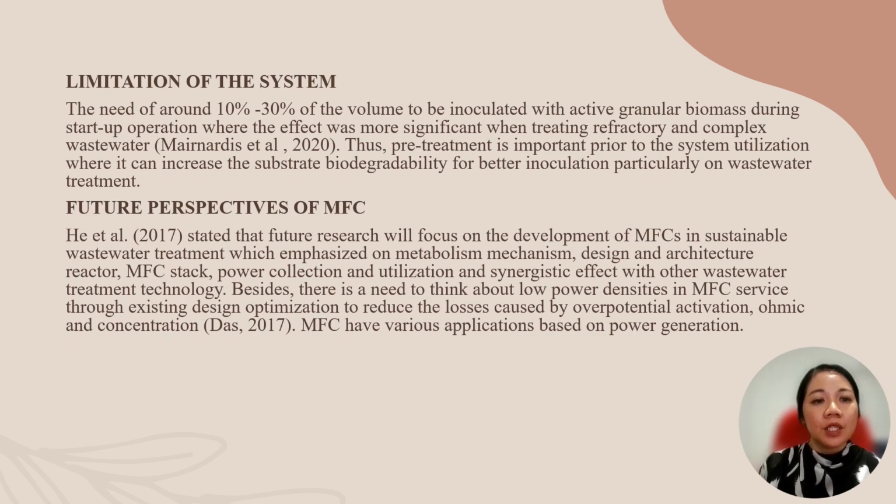Limitation of the system: the need of around 10% to 30% of the volume to be inoculated with active granular biomass during startup operation, where the effect was more significant when treating refractory and complex wastewater. Thus, pre-treatment is important prior to the system utilization, where it can increase the substrate biodegradability for better inoculation, particularly on wastewater treatment. Future perspective of MFC.